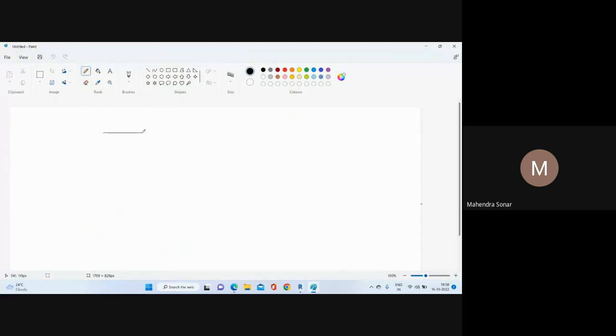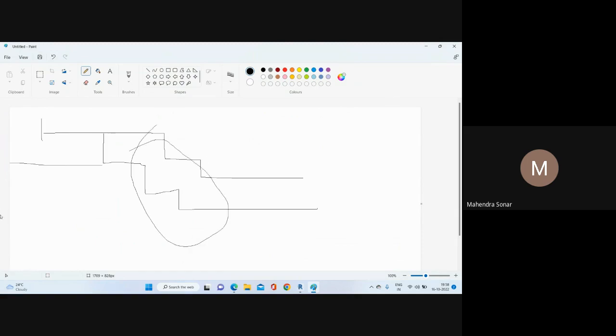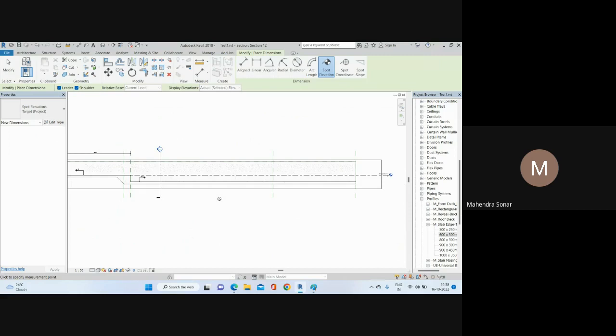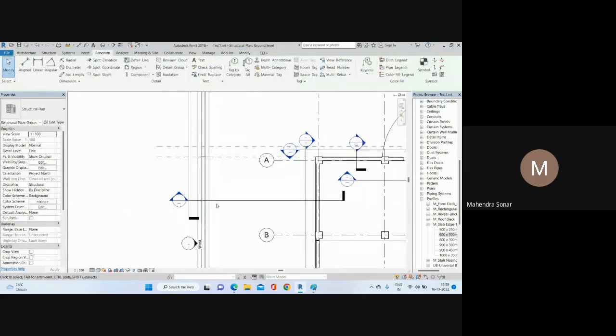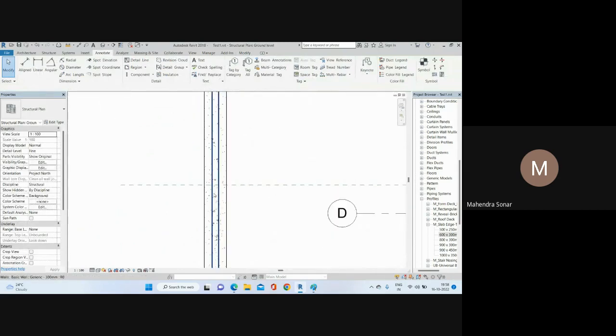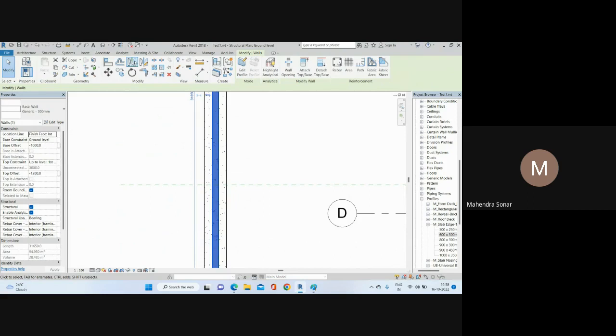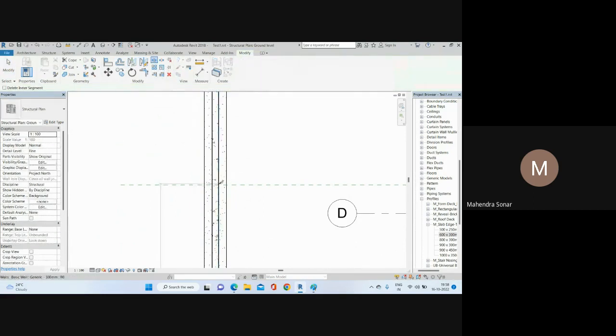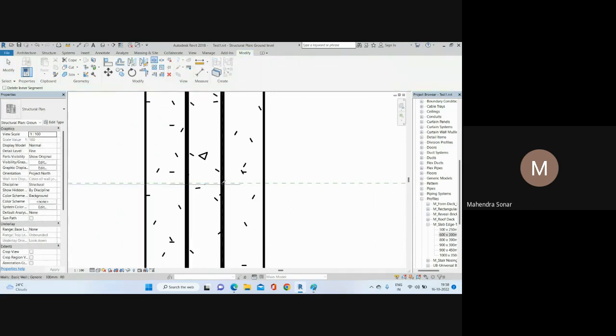So what we'll do, I want to add this type of footing like that. This footing is going up like that, right? Step footing here, and this continues. So you can create this shape also, right? So how to create? As usual you need to cut your wall first. We have offset here, right? So select your wall, go to split element, and select this wall at this level, at this point.